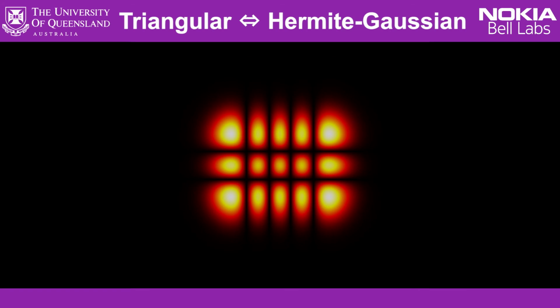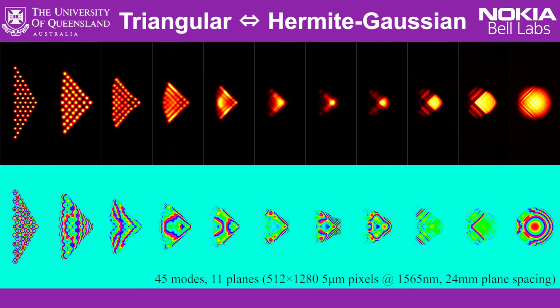Because all the modes need the same thing, you need fewer planes. Okay, so we've started here with a triangular array, which sometimes will be fine. Again, it's just a triangular slice of a densely packed hexagonal fiber array. But it'd be even better if it was a 1D fiber array, because that makes it very easy to come across. You can get 1D arrays which are very tightly spec'd in their tolerances. And it also makes it easier to get little micro lens arrays for collimating the spots onto the first plane. But the important point here is that we've got a good solution as our starting point.